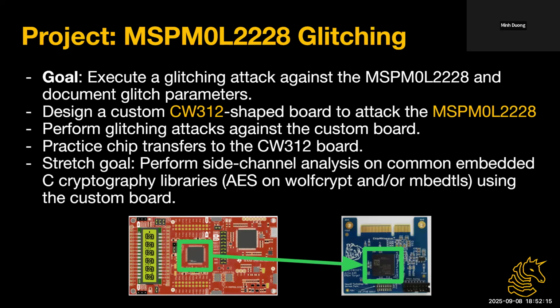Did you talk about manipulating the voltage like that? Are you talking about manipulating the voltage that's given to certain memory, like a memory bank? So basically, and we'll talk about the components of a microcontroller literally next next meeting, you know how a CPU has cores? A microcontroller also has cores. Usually each core will have a dedicated power line. It might not be exposed externally as pins, but usually you can find something to tap into, like the main voltage line, and you have to remove resistors and capacitors because they can mess with the voltage as you're glitching it. But if you do it right, then you can manipulate that core power.